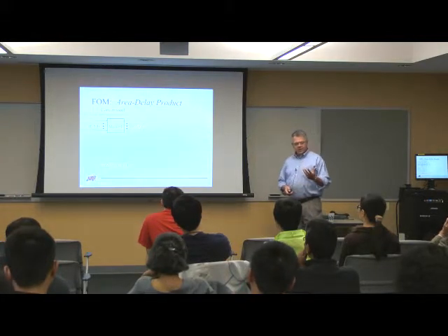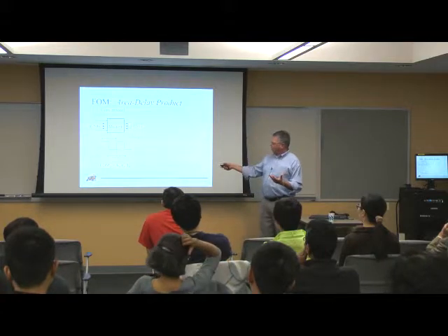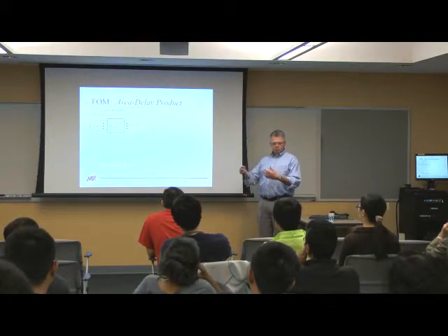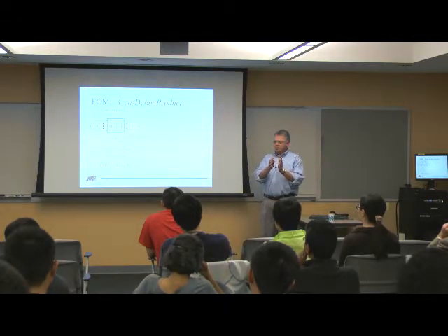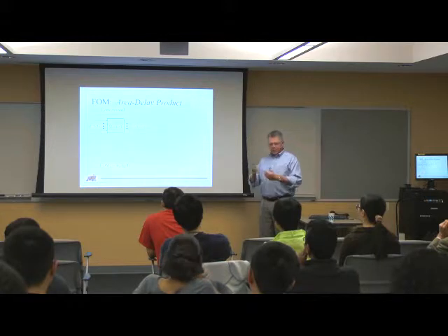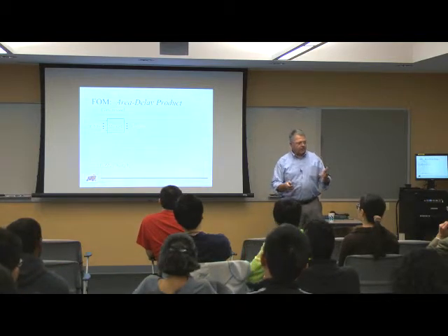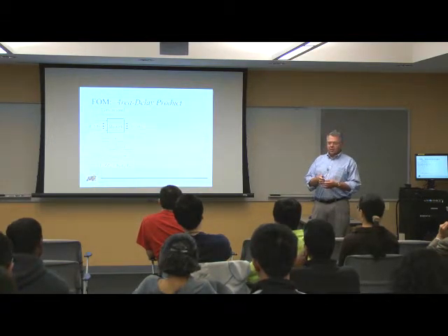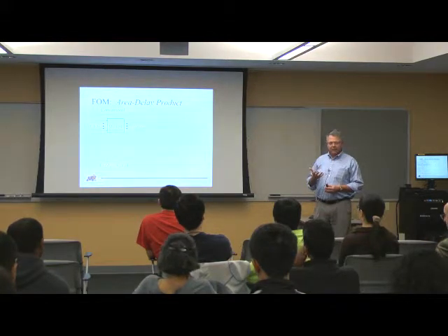The idea behind this is that I could make it go faster by spending more hardware and make this multiplier bigger. Do more of it in parallel, and I get a reduced time, but it costs me more. Okay, so this product says, what's that trade-off? You know, if the area of the multiplier grows by m squared and the delay reduces by m, then I'm going to see this grow faster than the performance that I get back out of it.